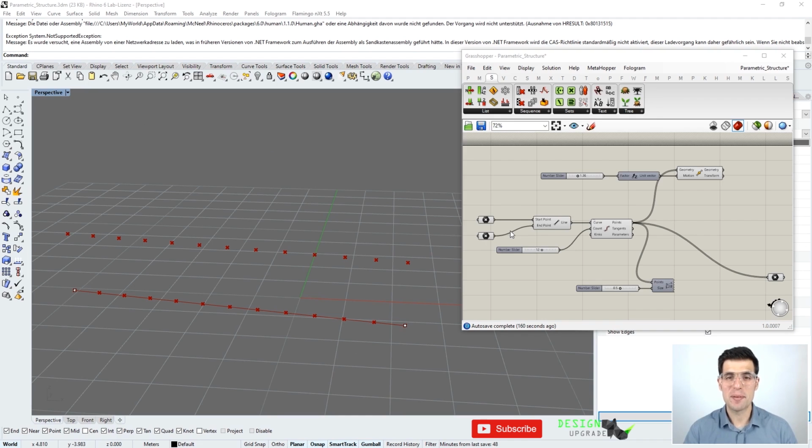But if you remember properly, these are not the nodes of our truss structure yet, because what we have to do is to remove every 2 points in the upper chord and also every 2 points in the lower chord in order to create the geometry that we are looking for. Which means that now we are going to start manipulating lists in Grasshopper.